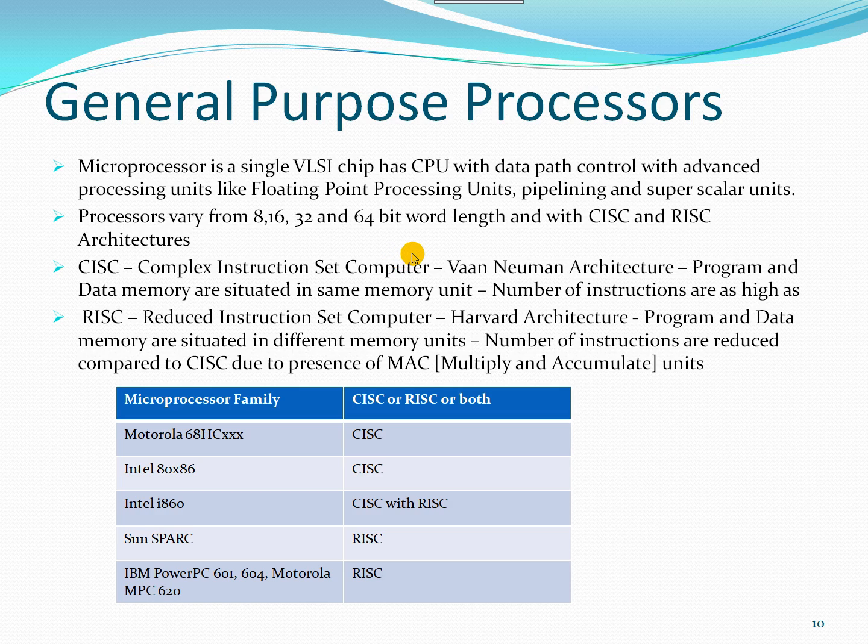CISC is the complex instruction set computer. They deal with the so-called von Neumann architecture, which means that program and data memory are situated in the same memory unit, integrated into a single board, and depending upon the instruction set which the programmer can model, that model is used for the CISC computers. And the instruction sets are very lengthy.